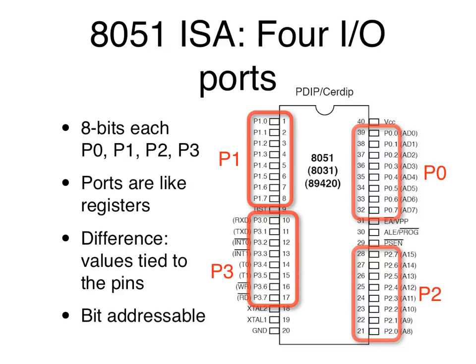Now, the 8051 has these four I/O ports: P0, P1, P2, P3. At least the space is defined for them. Later 8051s don't necessarily implement all four of them. They might implement maybe P0, P1, and maybe P2, sometimes even partially. Like the CC2540 actually has the address for P3 but does not have a real port for P3. That happens too. Okay.